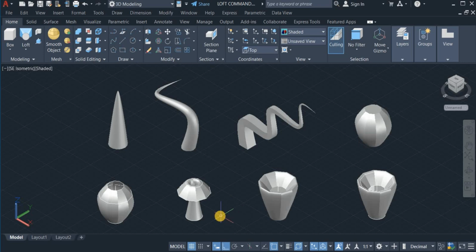And again, the lofting order also matters. So I can choose to loft the lower one first, next the second and the third, that is 1, 2, 3, or 1, 3, 2, depending on the order I want the loft to take place. Okay, so here's another one.